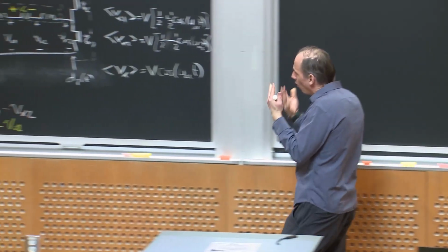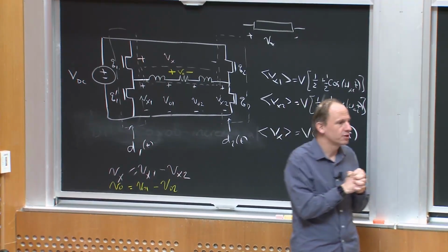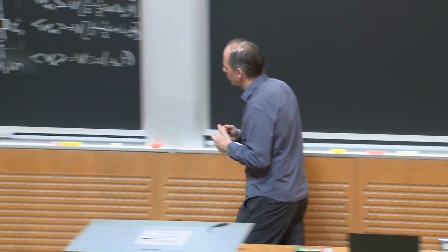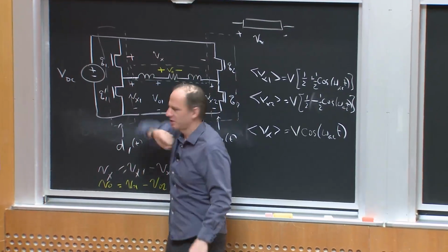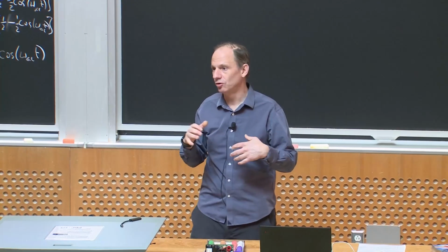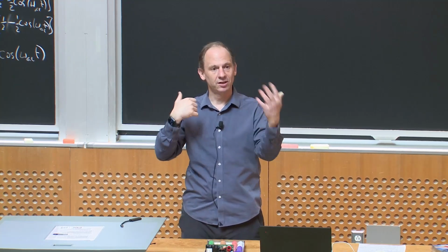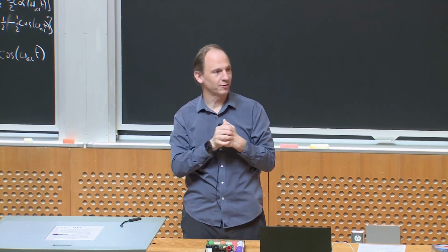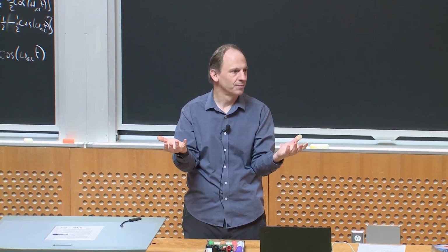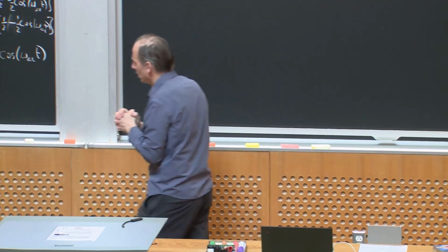Why do I mention that? One, just because it's another way to look at what a full bridge inverter does. Another, just as an aside, which we're not going to dive into, is that just because I used buck cells here doesn't mean that's the only converter I could use. So I could take two synchronous flyback converters, for example, and use each of those as a half cell and take the difference of their outputs and get a flyback-based inverter, or a flyback inverter. And people do that. So people use different topologies to do this.